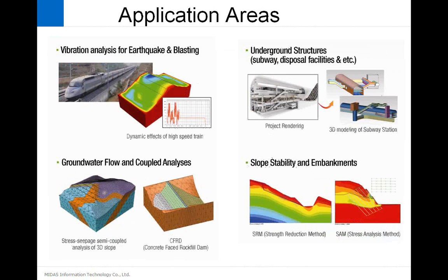Vibration analysis for earthquake and blasting can also be done in GTS. We can also account for the dynamic effects of high-speed train. The underground structures, the subway, disposal facilities, etc. can also be modeled and analyzed in GTS. The groundwater flow, taking care of seepage phases, and the coupled analysis can also be done in GTS. GTS finds its high application in the slope stability of dams and embankments.